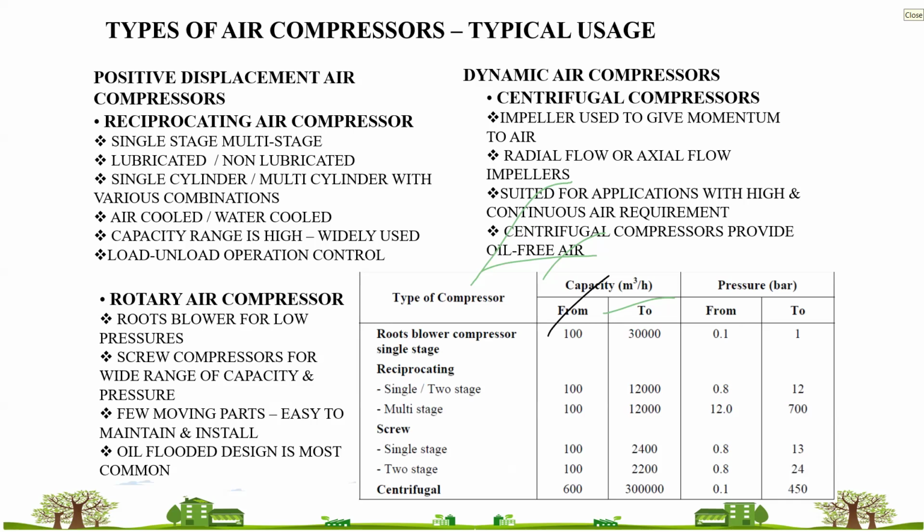Another concept is which air compressors are more efficient, air cooled or water cooled. Water cooled are more efficient, because in water cooled you can dissipate more heat, and water can carry more heat than air. You will require a larger amount of air to be circulated for air cooled compressors than for water cooled compressors.